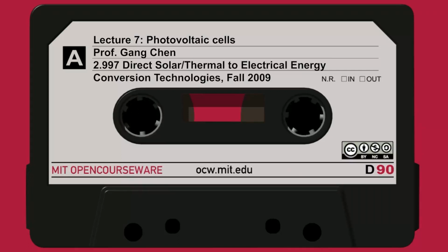And let's look at amorphous silicon. Amorphous silicon here. Okay. The real world deployed is about 6 to 8%. The best in the lab is about 12%, but that's with fewer junctions, not just amorphous silicon. And this is, say, copper indium diselenide, and the best is about 19%.